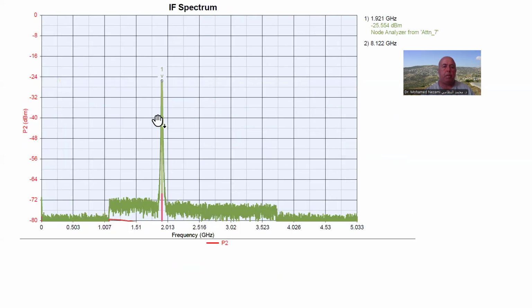And then the next thing is, I look at the spectrum of the IF, and it's very clean. From 950 to 2950, there's nothing. It's flat, just the noise. And the slope that is coming in from the IF amplifiers and filters, you're always going to get the slope, but we're going to leave this out until we start circuit implementation, where we would adjust with an LC type equalizer to equalize this slope.